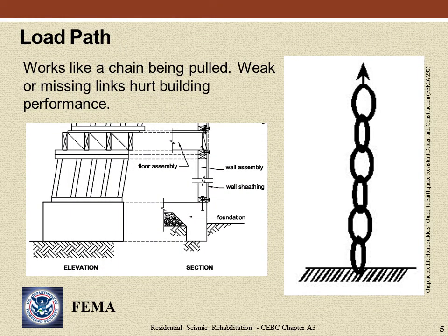When seismic rehabilitation work is being installed, the concept of a load path provides important guidance on completeness of the rehabilitation measures installed. A load path works like a chain that is being pulled. Each link is a load path connection. A weak or missing link will prevent a building from performing as expected.